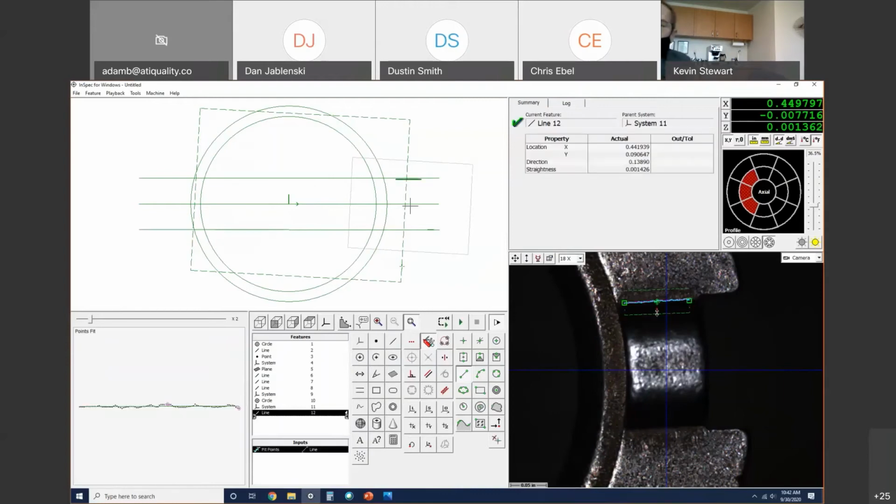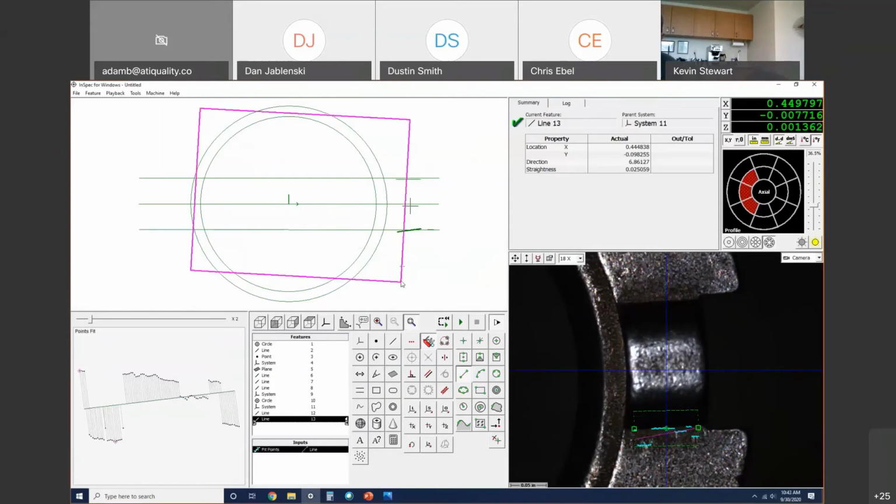Same thing, my red arrow is going towards where there's more contrast and that sharper edge. And here's a good example. You could see in this tool, since my red arrow is coming from the more gray values on the surface of this part, it's actually scanning a bunch of different edges on here, and you can see how crooked that line is in my schematic window. So I want to go ahead and flip that scanning tool.